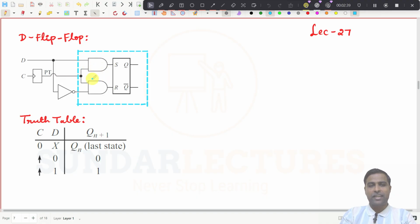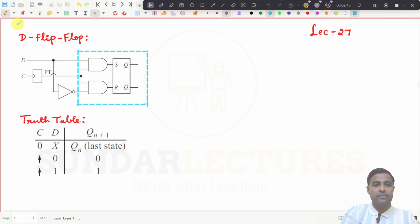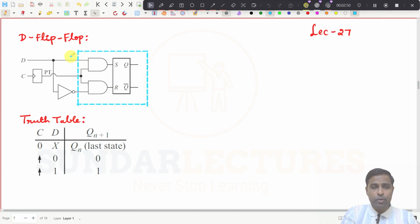If you give clock pulse, we can use this as an SR flip flop. This input is S, and this point is R. That is what we have taken. Anyhow, to give the clock pulse, we have added these two AND gates. That is what we have seen in the previous class.